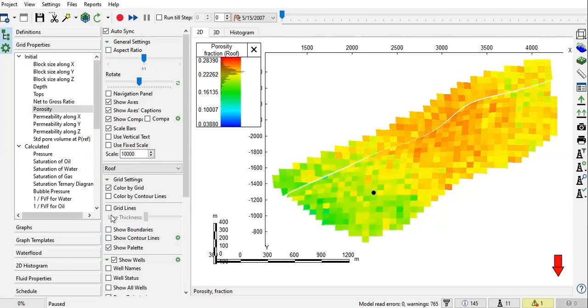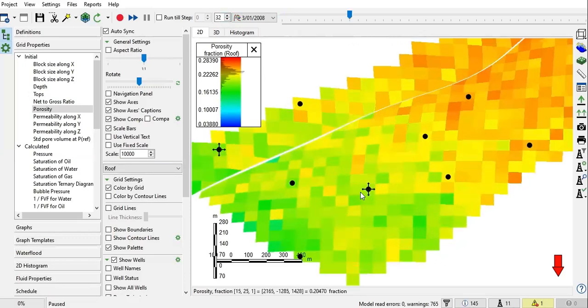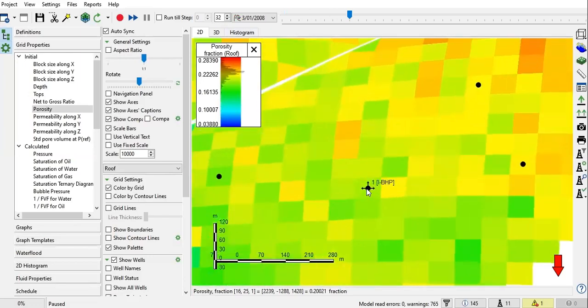And yep, okay. So that's the first thing that we need to do. And then let's go to time step. For example, let's go to time step 32. So it's very case specific. Okay, this is the sample. If we want to use the sample from tNavigator, we go to step 32. Why? Because in this time step, this well first converted from producer to injector.